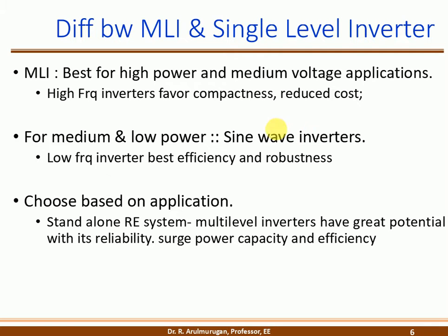If it is low frequency, then automatically compactness is not possible. Do you know, a transformer is also available nowadays, which you can look at on a power electronics board. It is called a high frequency transformer. The switching frequency of the transformer is high. So if a high frequency transformer is used in the power electronics board, the size of the circuit and the component level will reduce, for compactness purposes.